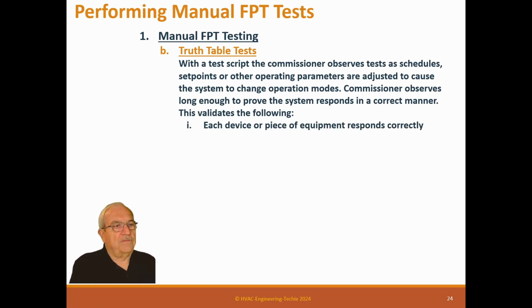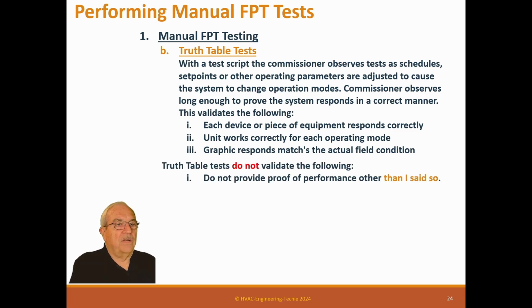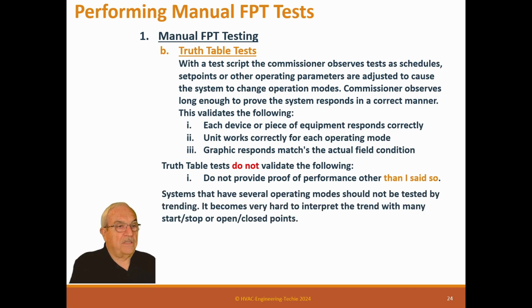This validates the following. Each device or piece of equipment responds correctly. Unit works correctly for each operating mode. Graphic response matches the actual field condition. Truth tests do not validate the following. Do not provide proof of performance other than I said so.